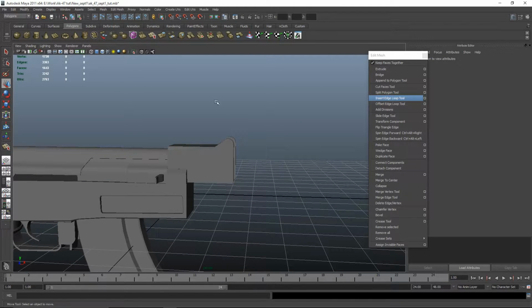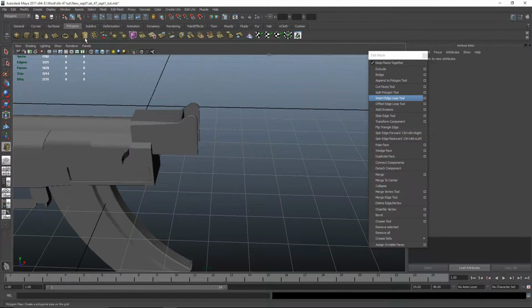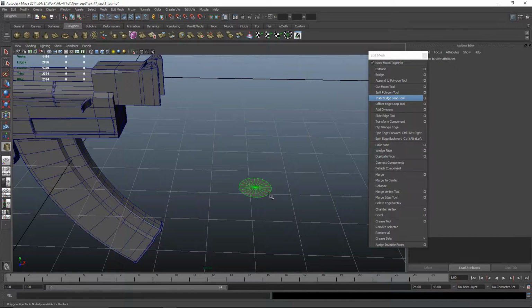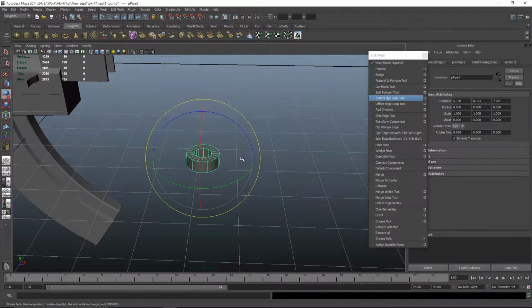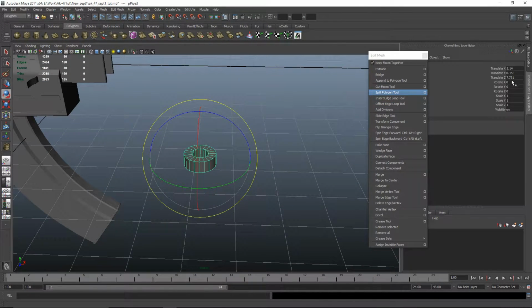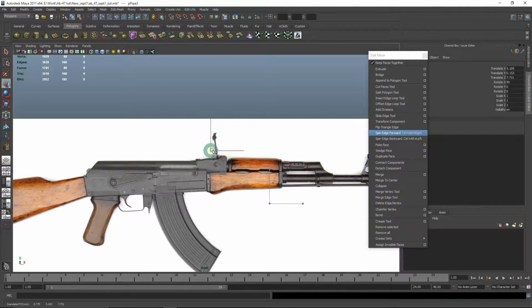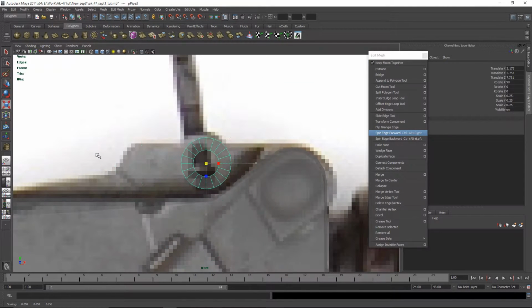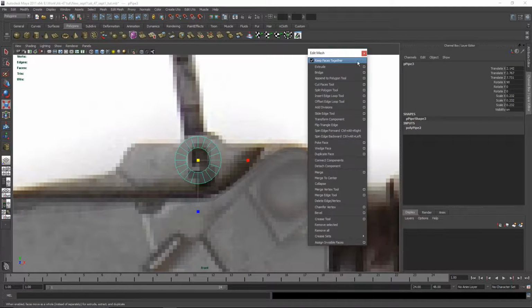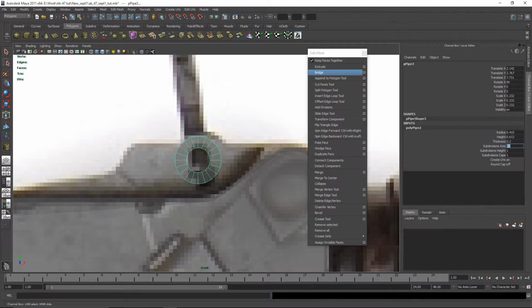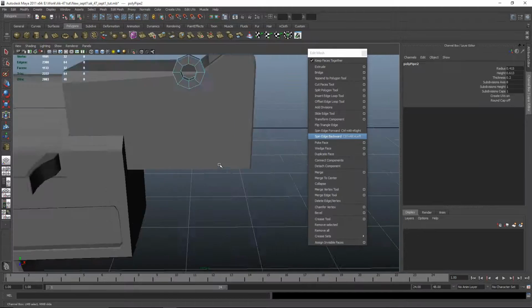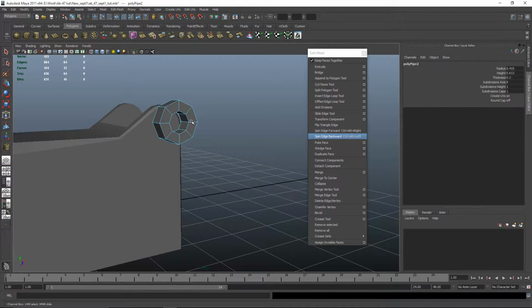And the next step is I'm going to use the pipe tool, which is this one right here, and just make something like this. Okay, and rotate that on the x-axis as well by 90 degrees. What we're doing is just making this little hole right here. So we want to remove pretty much all the subdivisions. I think have it on something like 8. Yeah, and then after we do that, we also remove the 2 edges on the sides as well.